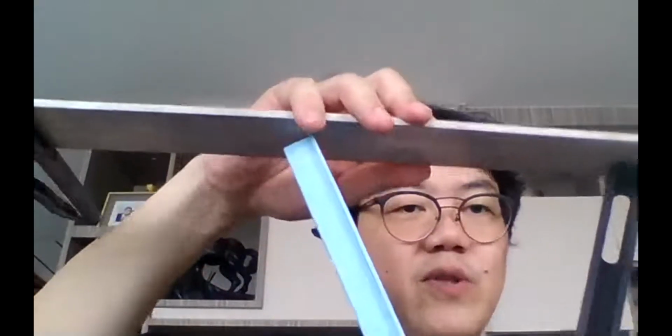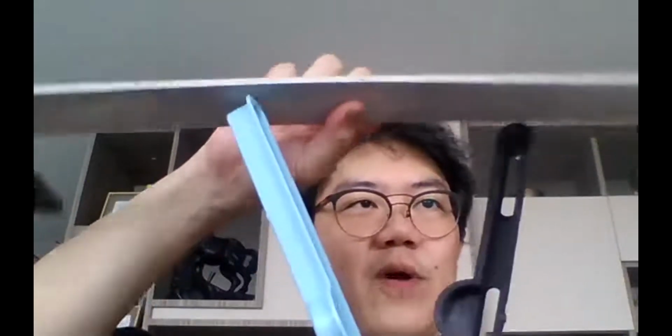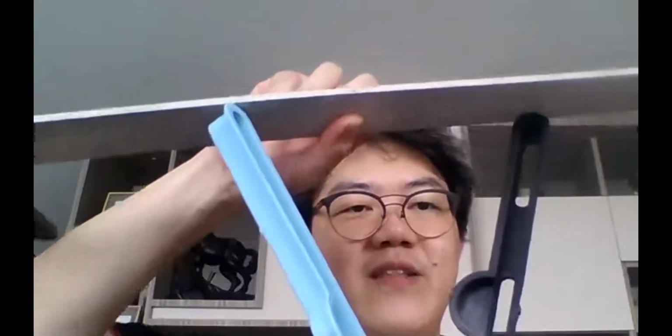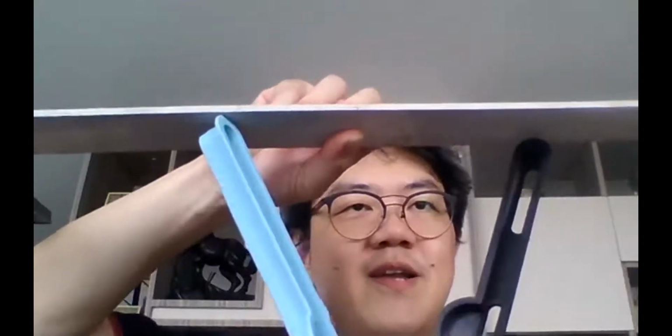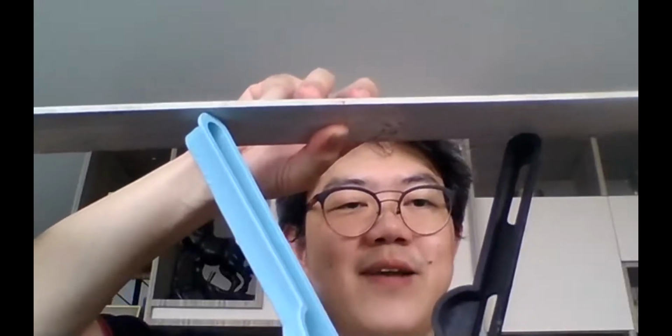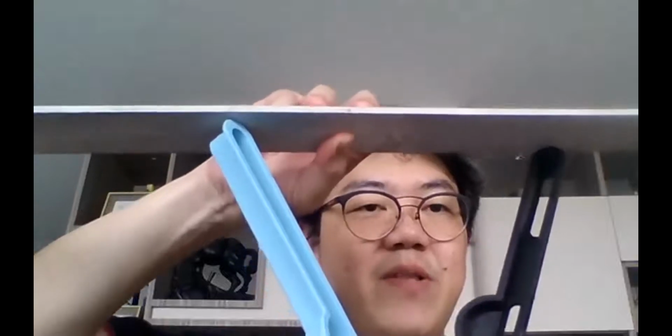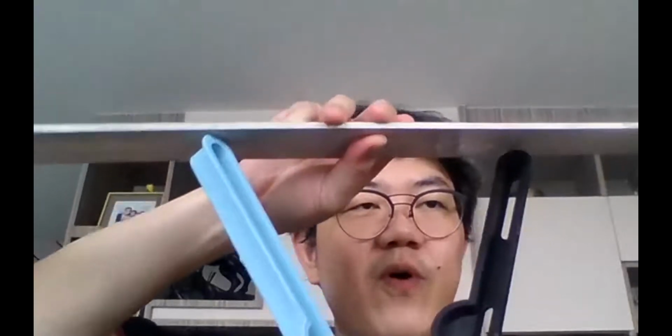If the buckling is going to occur up and down, this top chord can buckle between the two nodes, right? It can buckle between the blue member and the black member. So this becomes the unbraced length. But you see the axis of the top chord, it is just too much for me to bend it in one hand.